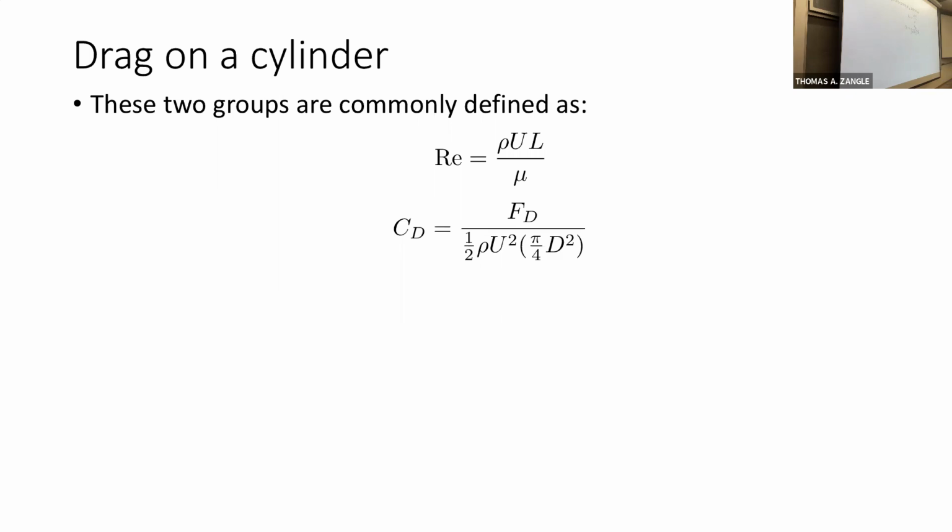Yeah, so in this case, you could check me, or check your textbook, and make sure this is actually dimensionless. And I guess it better be. It should be dimensionless. And what I'm saying is that we could have used the Buckingham pi approach, the dimensional analysis approach, to derive something that looks like this, but doesn't have this pi over 8 constant in the denominator. It still would be dimensionless, and we could still use it. It's just that it wouldn't match the definition in your textbook of coefficient of drag. Does that make sense?